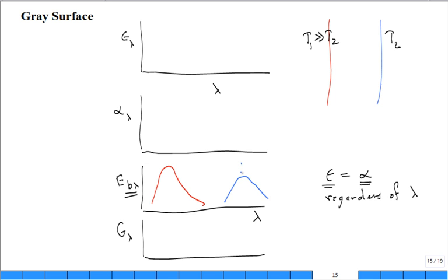I know that I'm grossly exaggerating. There's a great height difference as well as a shift. So you need to put this on a log scale over here for the black body. Okay, well, that's the emission from each of those surfaces. What about the irradiation, especially for surface 1? The irradiation on surface 1 is the emission from 2, isn't it?